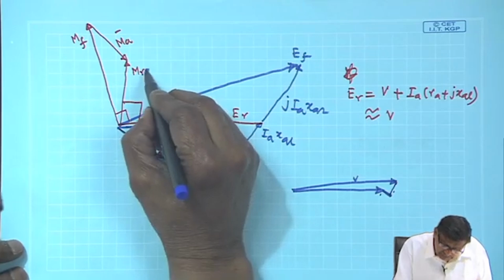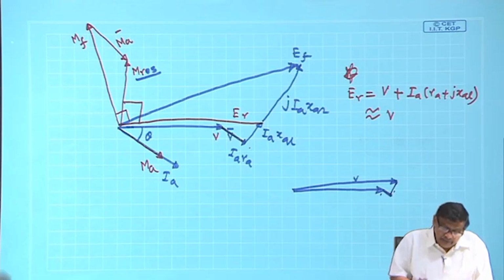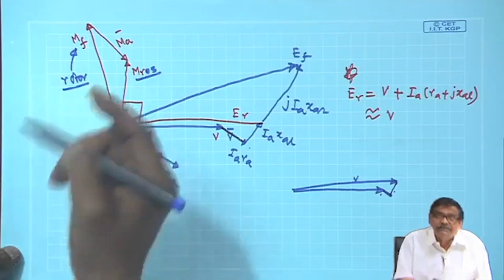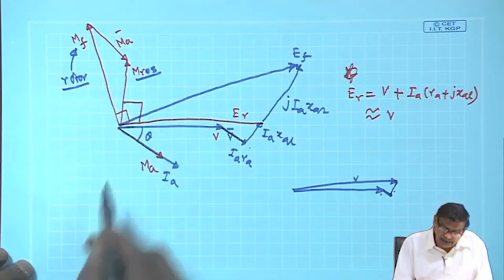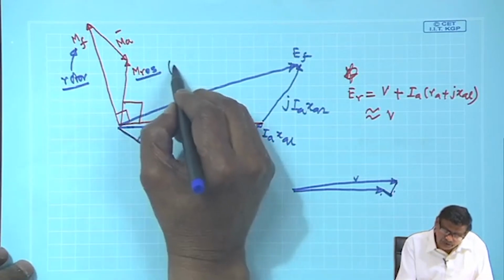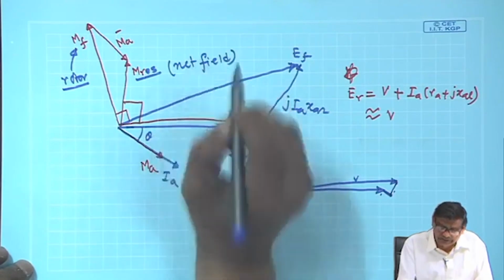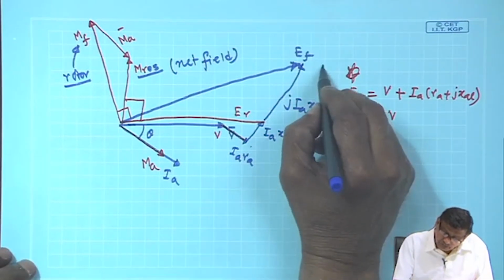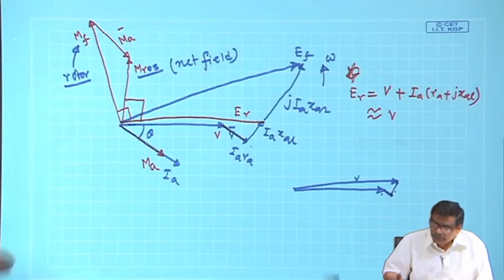Mind you, this is the resultant field, do not consider this to be the rotor field, okay? Resultant field. Rotor field is which one? This is the thing. Rotor is the DC winding, it carries DC current, that is how we have assumed. This is the rotor field, and this is the resultant field, which I called earlier the net field while discussing in general about the machine. And all phasors are moving, and also the rotor is moving with the synchronous speed ns or 2 pi ns.